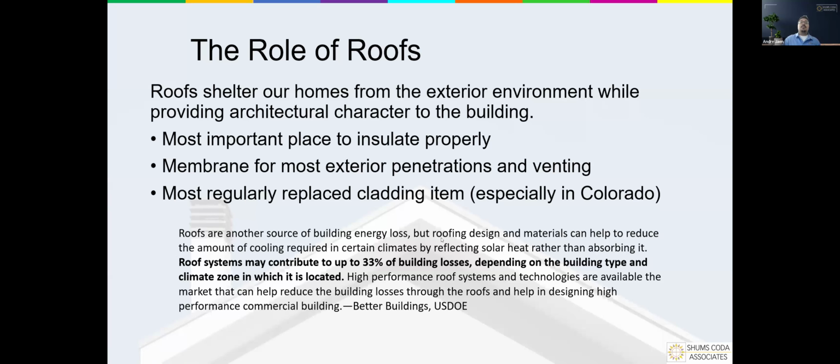We're going to talk about how some of the tactics used previously for ventilation, some of the misunderstanding about how to install ventilation properly, has definitely been a contributory factor towards that. I can definitely agree with you that I have been in my fair share of attic spaces, for instance, where I have seen gable end vents that have become sort of intrusion areas for water to get into the rest of the assembly there.